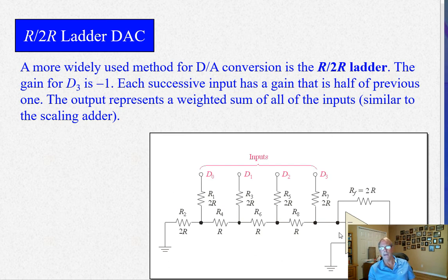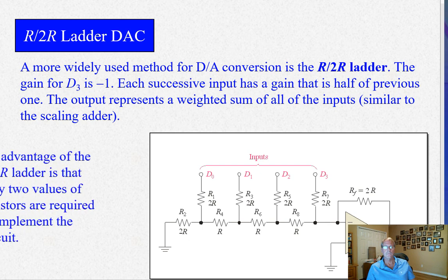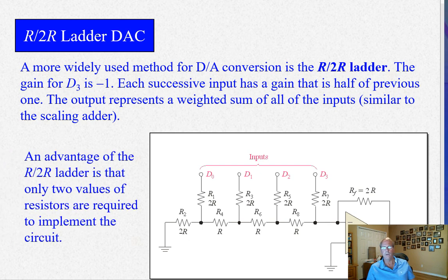So that's how these are made. They're made on a common piece of silicon. Even the OpAmp is in there. All right, so these R2R ladders and DACs are very accurate. There's some math you can do on this too. Usually in my regular face-to-face class, I don't do the math too much because it's really not necessary, but just understand that an R2R DAC does have a high accuracy and uses all the same resistor value, which makes it very practical.